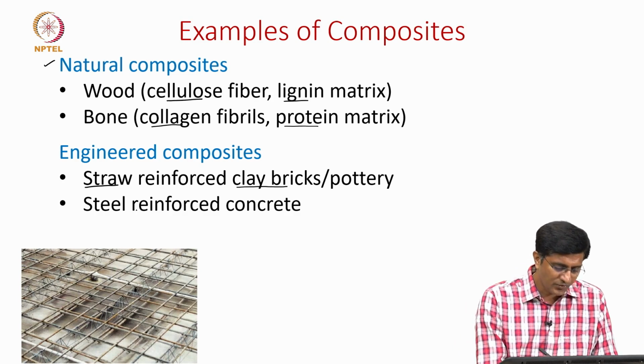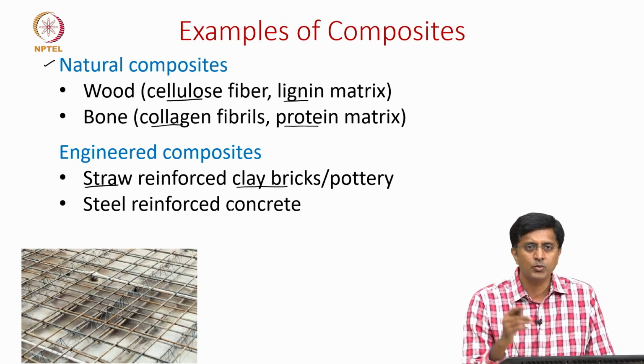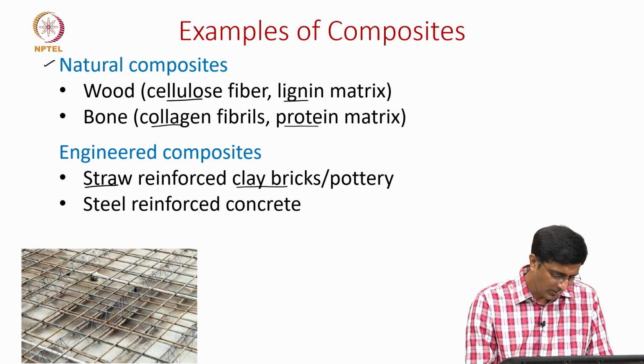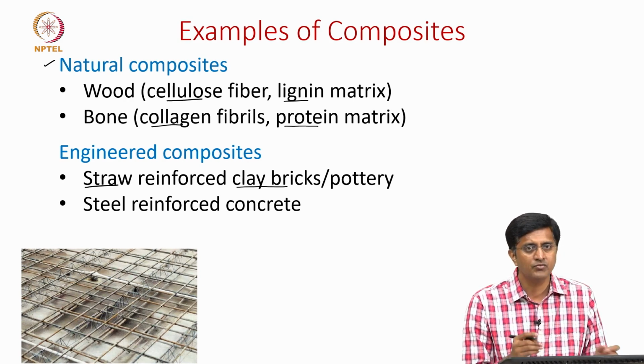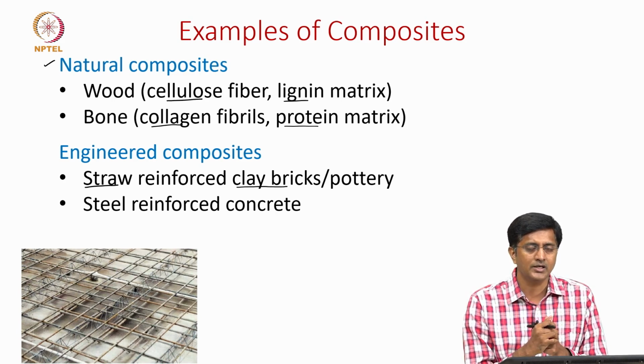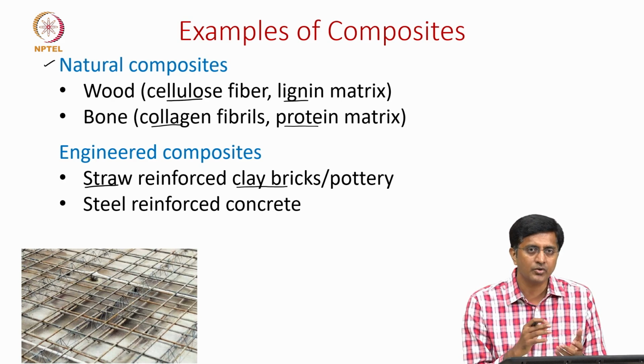but coming to the present age, we have been using composites such as steel reinforcement in concrete. Most of the buildings we have around are made up of steel reinforced concrete. We have steel rebars which can take tensile loads, which are reinforced into the concrete. Concrete is good to take compressive loads, but it is weak in tension. So, because of this steel and concrete combination, now they can take both tensile and compressive loads.